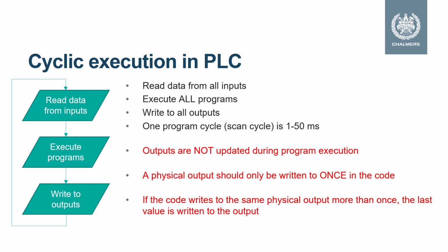Programming a PLC system differs a bit from programming, for example, a microcontroller. The execution in a PLC is cyclic. It's using an infinite loop. It's always running, well, until we stop it, from top to bottom, top to bottom, top to bottom. We always start by reading data from the input ports, then we execute all the programs in the specific order, and then after that, the PLC system writes to the outputs.